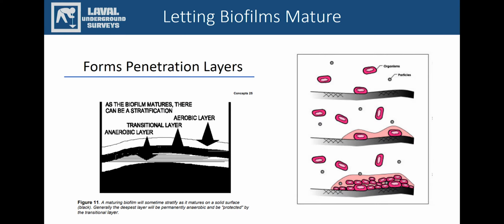As the biofilm matures, stratification of the slime occurs. The demands of the biofilm for oxygen exceed the amounts being carried into the water flowing by. Consequently, the deeper layers become oxygen starved and turn anaerobic. This causes the microorganisms to flourish under environments free of oxygen, ready to dominate. Two primary layers are created. Aerobic organisms form a layer closest to the water, which is their source of oxygen, and the anaerobic move to the deepest layer, where the water doesn't penetrate. In between, there is a transitional layer that's sometimes oxidative, but sometimes reductive.